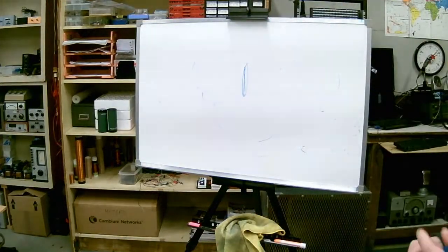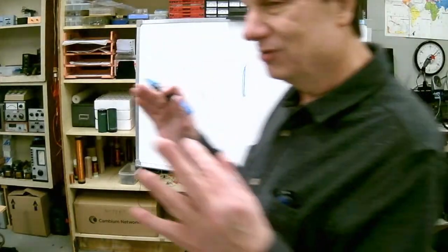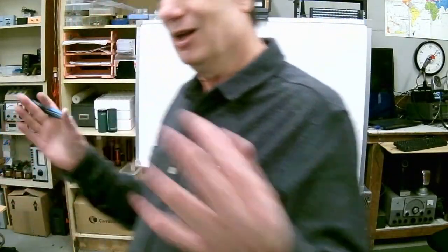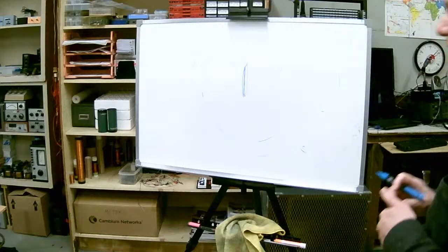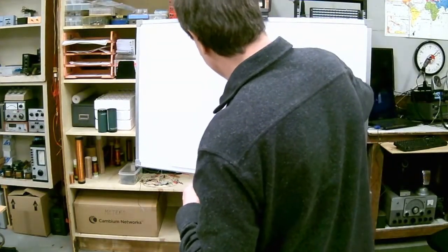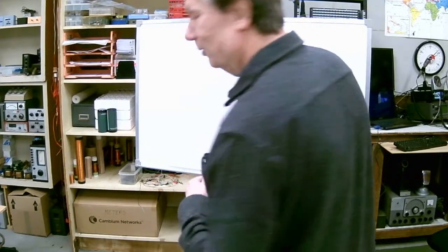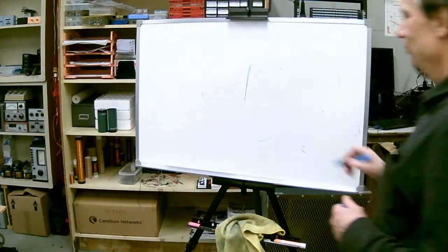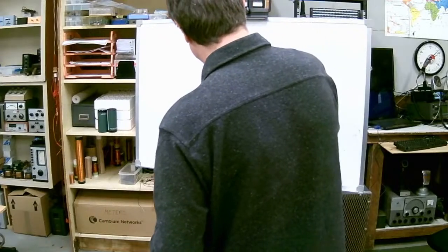They folded it there, which raises the impedance, because whenever we have other elements near it, it's generally going to lower the impedance. They have to compensate for that, so by using a folded dipole, the impedance is raised. But that doesn't help us understand the actual radiation, so we can just use a dipole there.